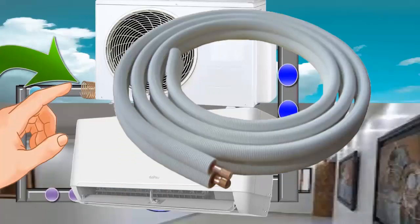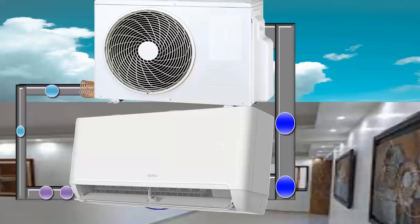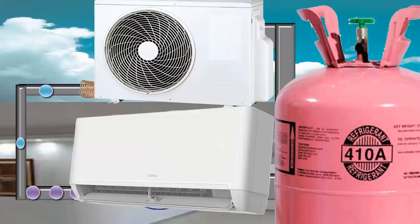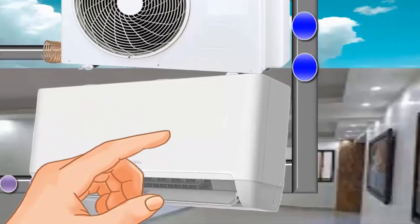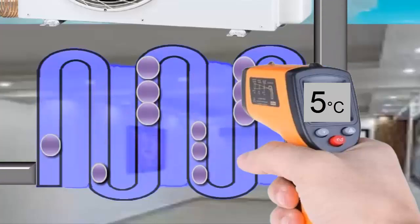The pressure of the R410A gas in the evaporator unit, indoor unit, during operation is approximately 122 pounds per square inch, psi. At this pressure, the temperature of the R410A gas inside the evaporator is around 5 degrees Celsius. Refrigeration technicians refer to this pressure as low pressure, and it is measured with the blue pressure gauge.